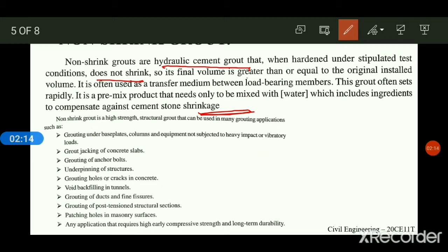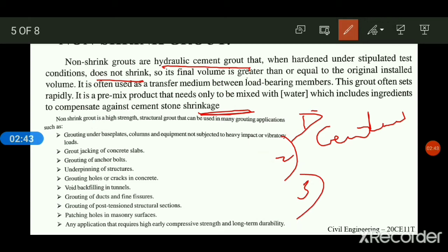The composition of grouting material mainly includes the following components: cementing material, early strength components, water reducing components, thickening and water retention components, aggregates, and finally, intumescent components.